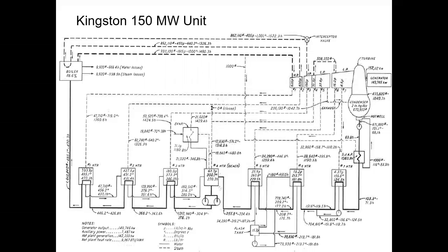Not sure what pressure, but the pressure falls because this is the highest pressure extraction, and it goes into this one. So on the shell side, I have lower pressure here, so why do I pump it? I don't. I just let the pressure difference between the feed water heaters move the condensate back.